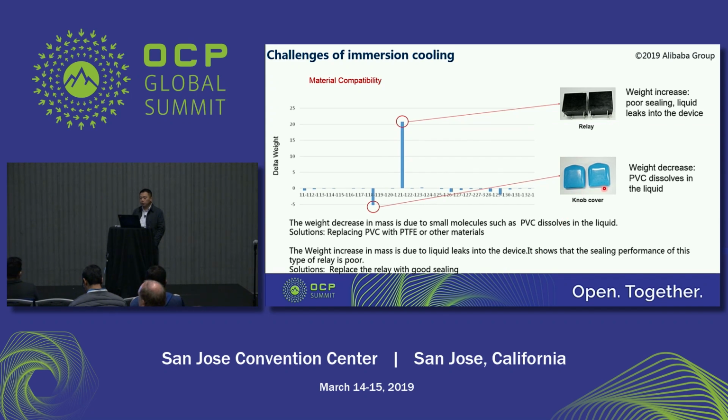Some materials, like this cable cover in liquid, we found degrade, because PVC dissolves in the liquid. So for this, the solution is that we must replace PVC with PTFE or other materials.